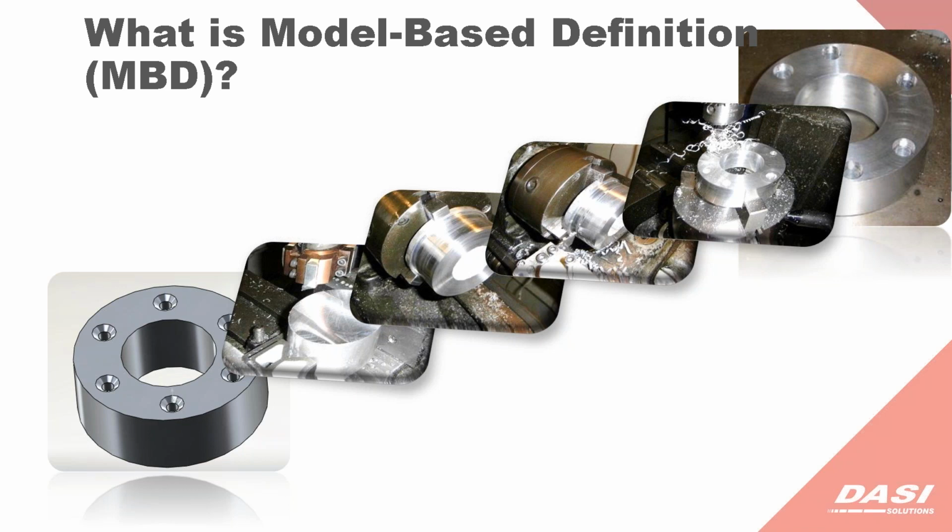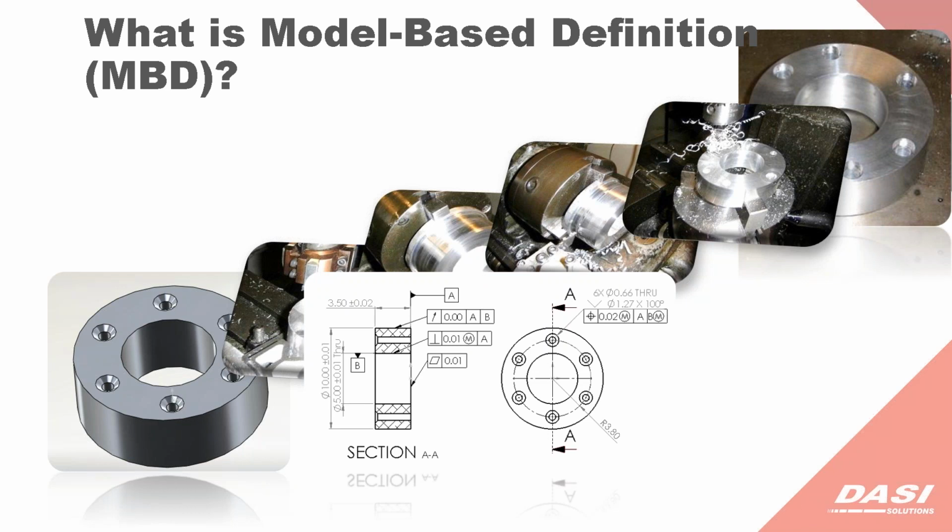In most cases, we start with a 3D CAD model, and then we have to spend quite a bit of time and effort building this thing called a drawing. In the drawing, we detail all the individual things that we need to talk about: dimensions, call-outs, different holes. We need to spec all of this out, including the datums, the tolerance values, and all the details that we want there. And if our drawing is ambiguous enough, we'll have to have a couple of conversations with our machinists so that they understand exactly how we want to tackle this so that they can build it.